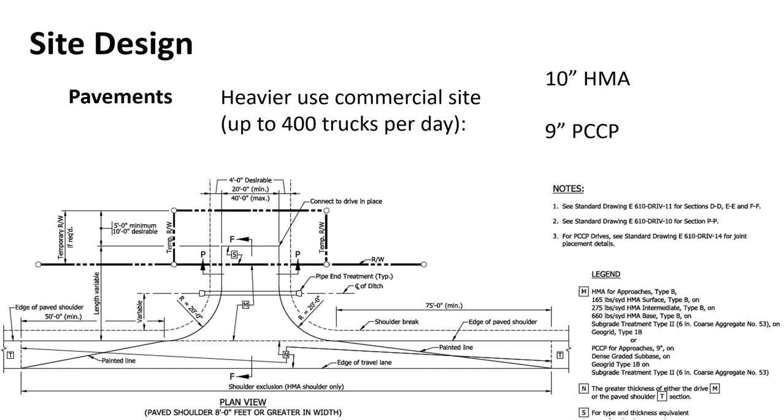And probably more. So you would probably design that like a true road. You would do the analysis because that's a lot of trucks coming in and out of that. The concrete plant, sure, you're going to design that like a real road. But 400 trucks a day is going to cover almost everything else. Even the UPS distribution warehouses don't have 400 trucks a day, right? At least one here in town, they literally have like 6 semis and then a whole bunch of little trucks, which don't count for that, and are much lighter. So that's all they have, and that's hauling all those packages in and out of a local distribution center.